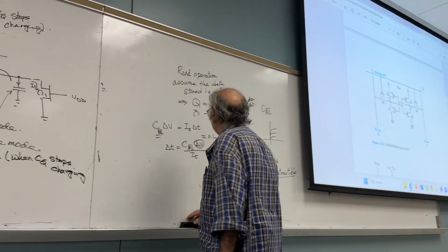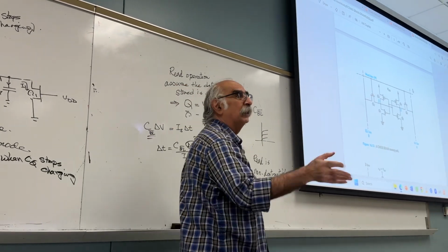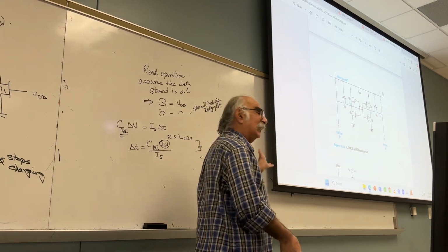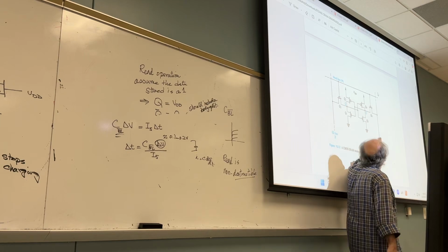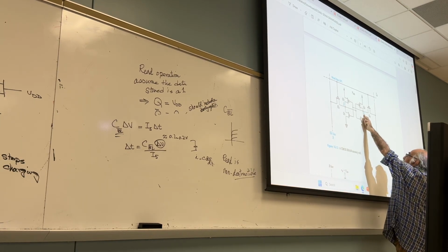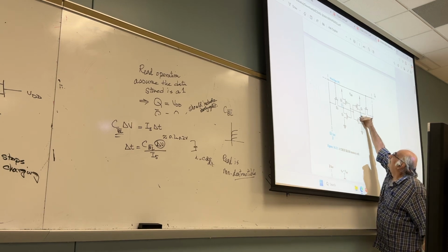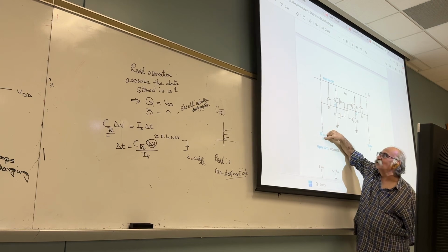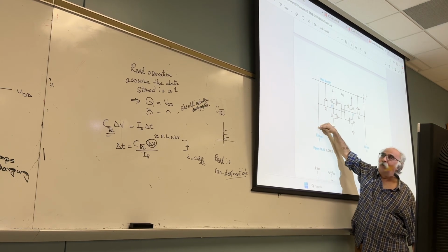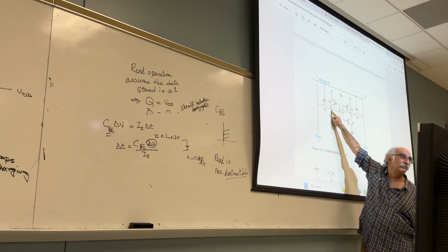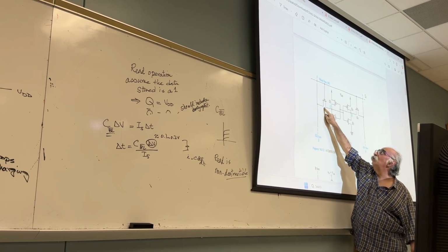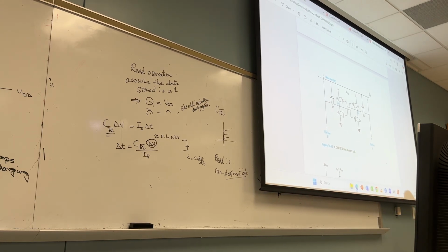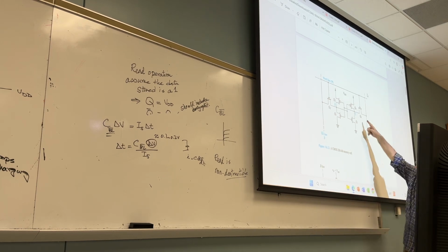Now the read operation. By the way, reading a 0 is the same thing. Do you agree? In this case, if there is a 0 here, what do I take? This one will not conduct, assuming that this one is VDD. Why? This one's VDD, and this one is VDD, which means there is no voltage difference between them, no conduction. This one conducts. Which transistors would I then look at? I would look at this and this.